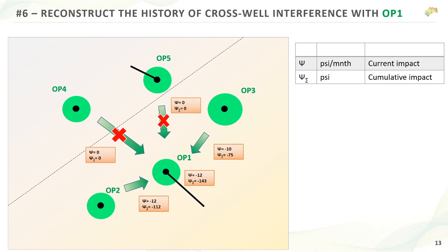So if your well has been producing stable ever since it's been launched, it would be very hard to say if it's impacting another well or not, right? Because the pressure would just smoothly fall down, and it could be due to reservoir boundaries, or it could be the impact of these wells. And there is no technology in the world which could actually say which is which, right?